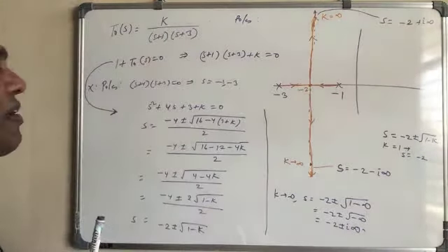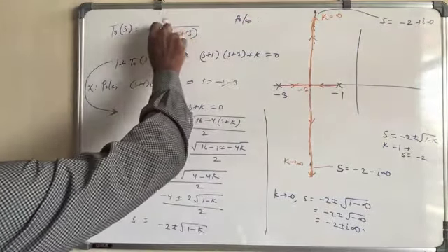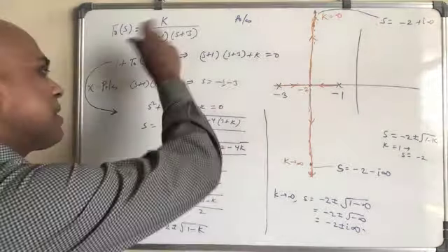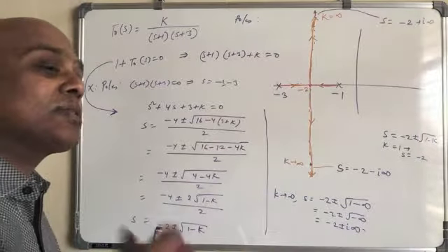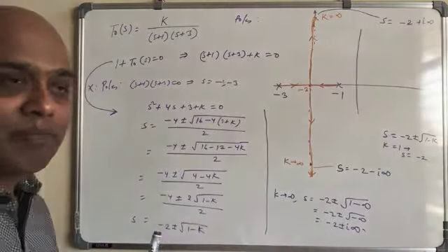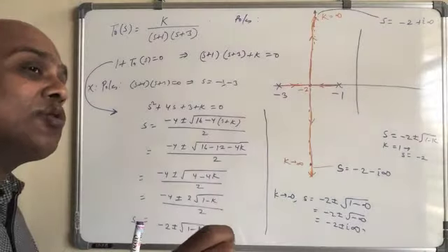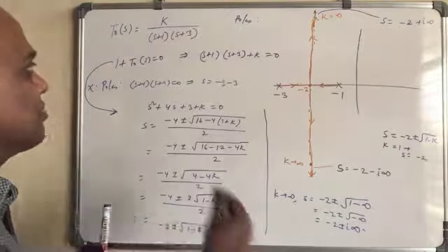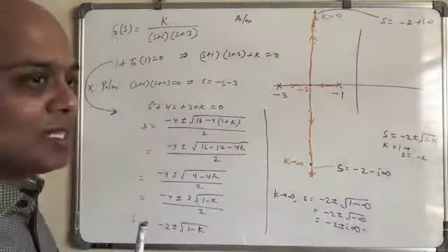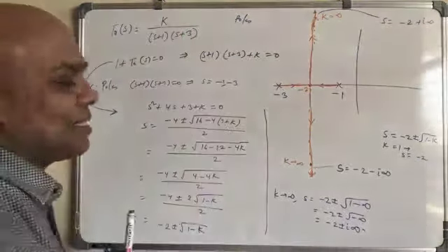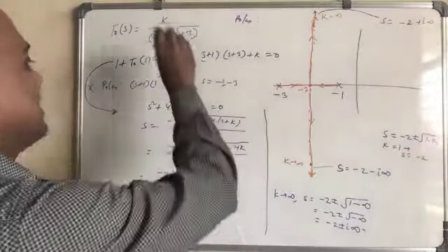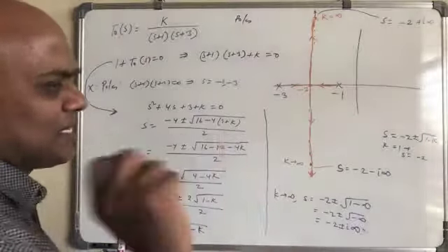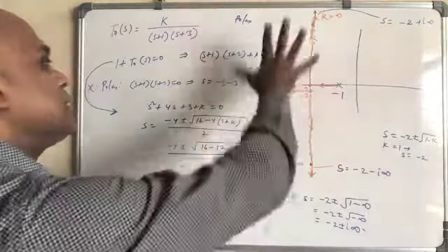Any open loop transfer function may have a gain k, which is a variable, and that may come from the proportional control that you have put, for example, or the feedback loop. The feedback transfer function may have some gain. So this gain is very important because it can control many things. Hence the idea here is how to change the gain. Just controlling the gain is going to control a lot of things.